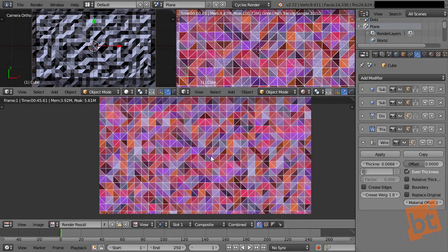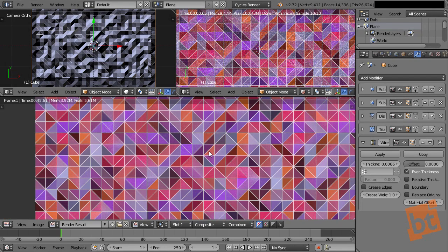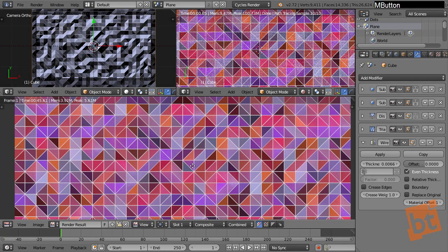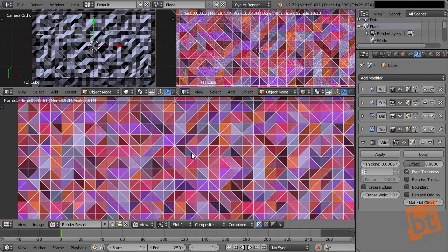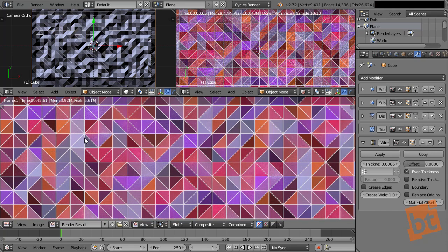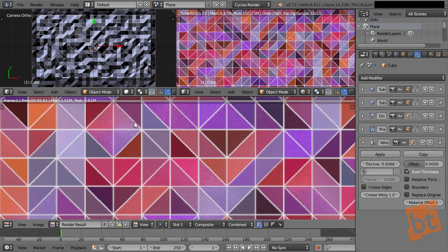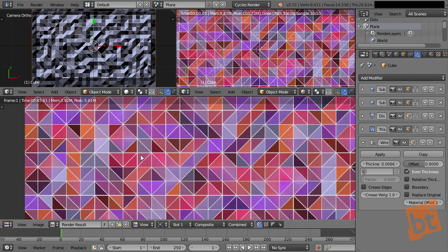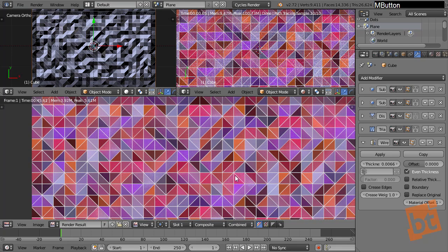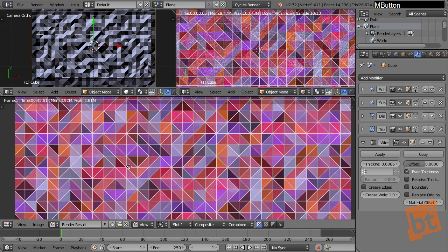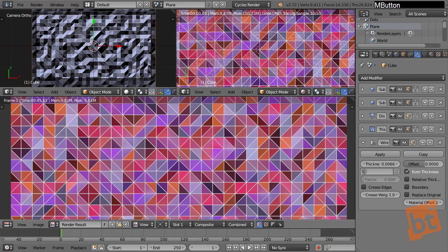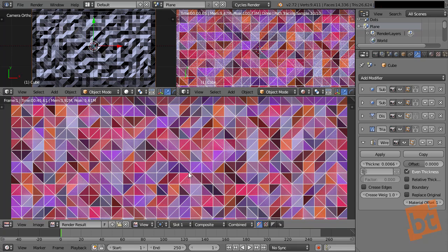All right, the render is done. You can see it's looking pretty nice. This is the full size. Okay, it's only 50%. And for the final render, we may want to increase the samples because we are getting some noise here. The reason for this noise is mainly because we have used a glossy shader, which takes a little longer to render. But the result is better than the diffuse. So I like it more, and I prefer to wait a little more for the render.